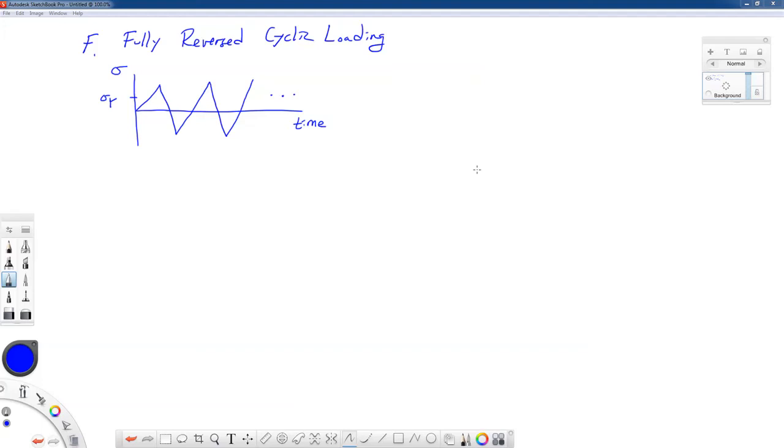If we were to look at the stress-strain plot, I'll draw this out to the side. We have our initial loading. Okay, so now we're at this position right here. We'll call that position 1. We talked about how when we unload, we initially follow the slope of the initial stress-strain curve. But something kind of interesting happens. If this is the negative of our yield stress,